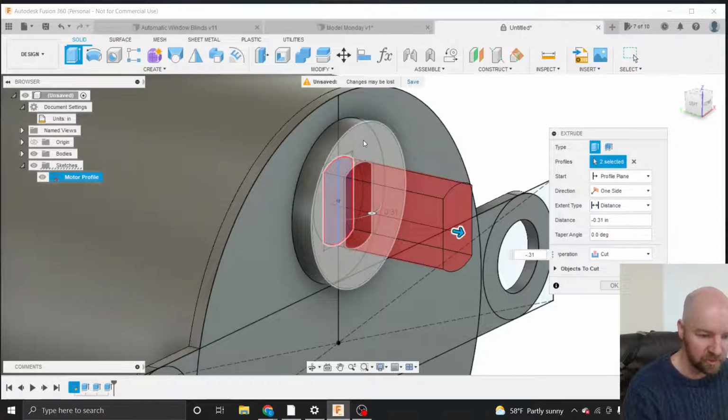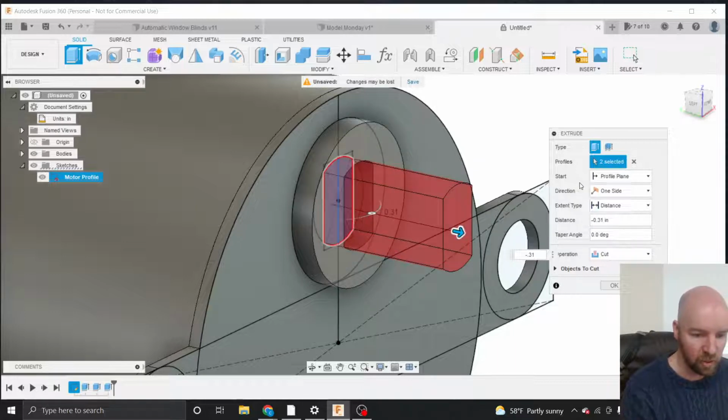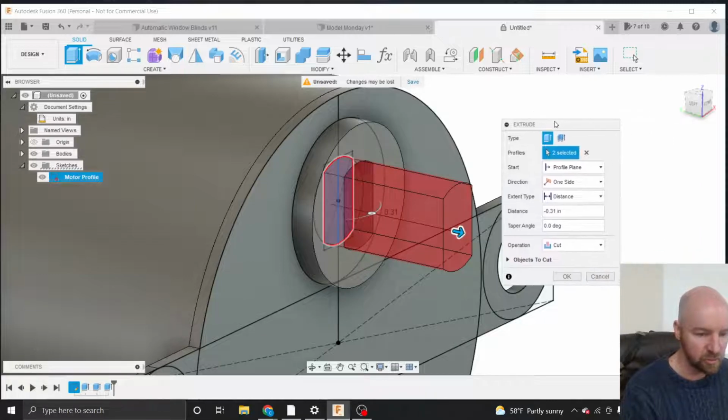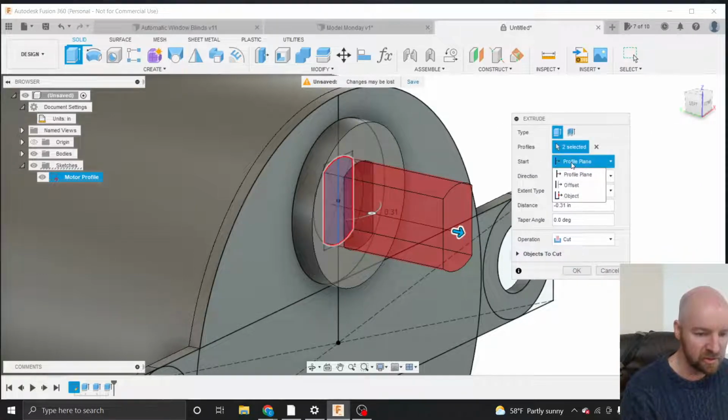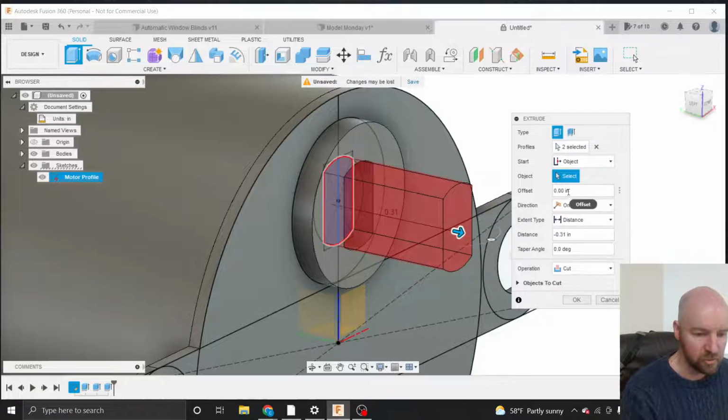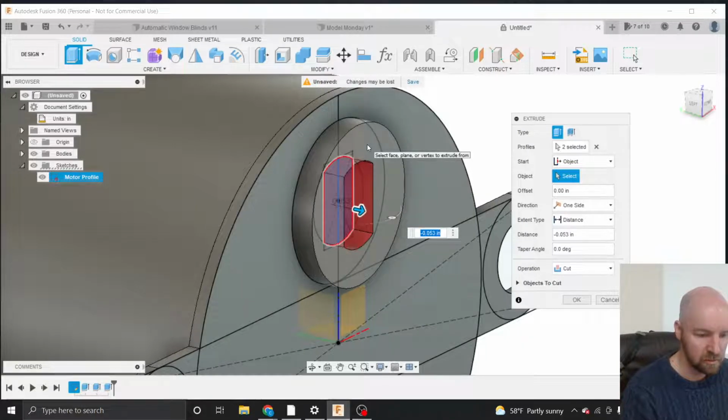So in my extrude window, instead of starting from the profile plane, I'm going to choose to start from an object. If I choose to start it from an object, the object that I'm going to select is...